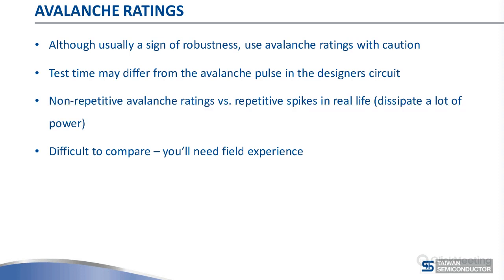Lower voltage Schottky have specific mechanisms to protect against avalanche, and these components are completely different from, for example, MOSFETs. MOSFETs have bulk breakdown, so the whole die helps you dissipate the power, whereas in a rectifier sometimes all the energy flows on the edge of the die, and it is definitely less robust. So these are some of the things you can compare and see in your datasheet.